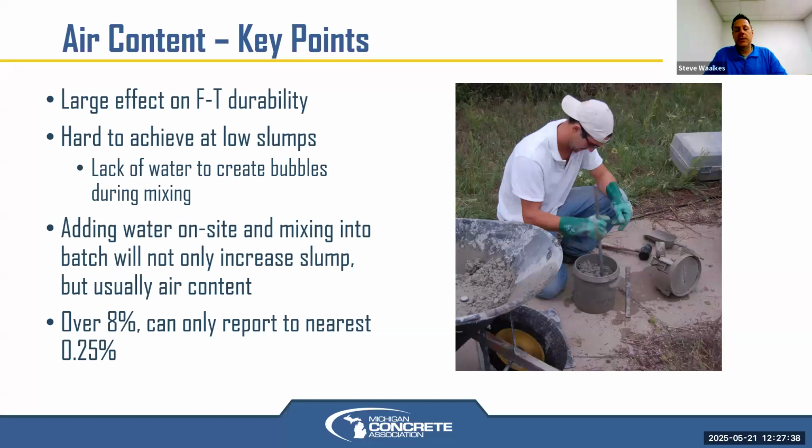And then that's what it does. It tells you the stability. The problem with it is the precision and bias. There's research that's been done and published, I believe by AASHTO. The precision and bias is equal to the actual number you're reading. So the 0.2 psi is kind of what you want as your delta between those 2 curves. That's a good SAM number, but the precision and bias is plus or minus 0.2%.